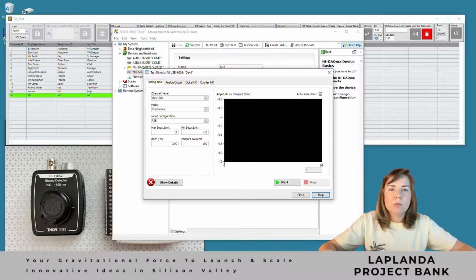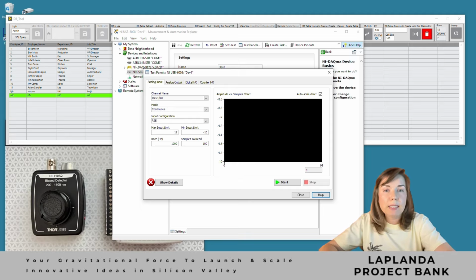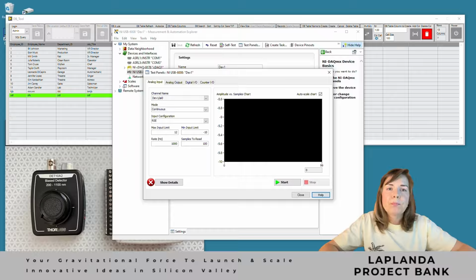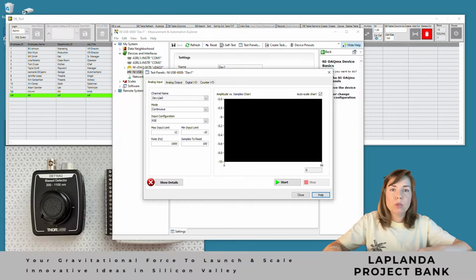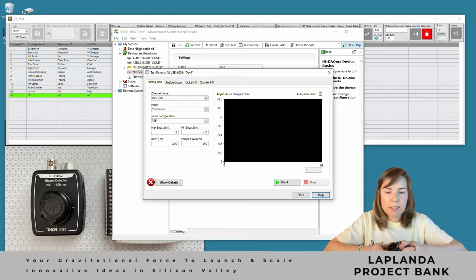For our USB device, there is a limitation on the input voltage for the analog input, and that limit is 10 volts. Of course, as users, we are protected from making mistakes both by the USB device manufacturer and by the driver itself. Let's see what the maximum voltage from my sensor can be. I disconnect the BNC connector from the photosensor, take out the battery, and check what maximum voltage can be applied from my photosensor. Why do I know that a higher voltage can't happen?